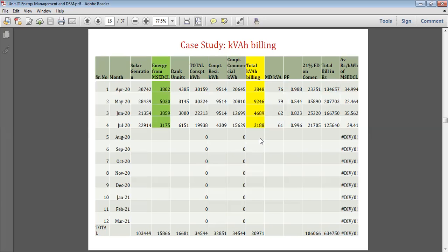So if you are maintaining the power factor, the maintenance of the switchgear will be smaller. So these are the technical advantages of maintaining the power factor. Whereas the economical advantage, if you are maintaining the power factor, is that your maximum demand, which is going to be measured in kVA, will be smaller. Your kVAH will be smaller, so ultimately your electric bill will be smaller. So it has a key role in the technical as well as the economical advantage in energy management.